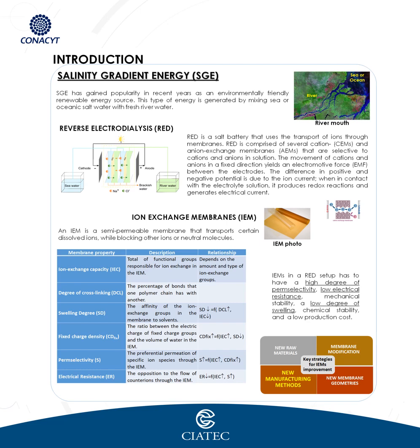The relationship between these characteristics of ion exchange membranes and their electrochemical and mechanical properties for RED application are summarized in this table. We can see that the properties all depend either directly or indirectly on the ion exchange capacity and degree of cross-linking ratio. These two membrane properties depend on the base material, synthesis method, and the experimental conditions.